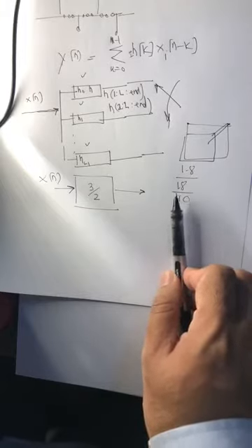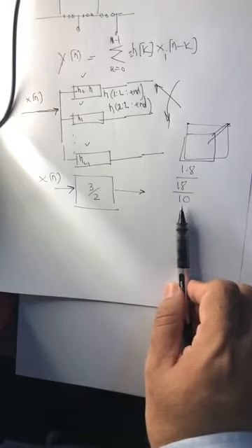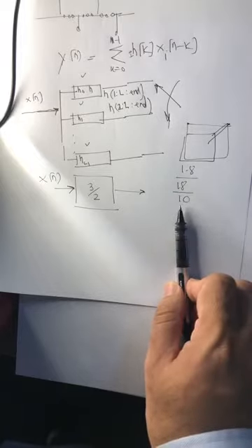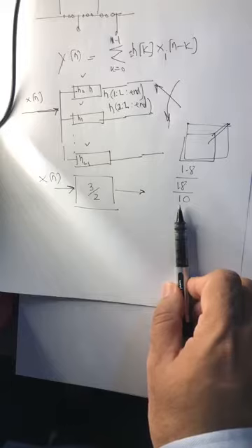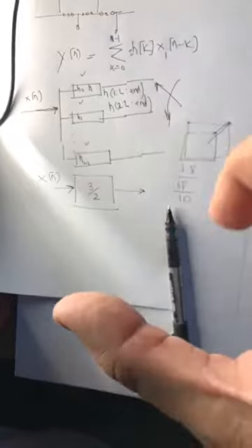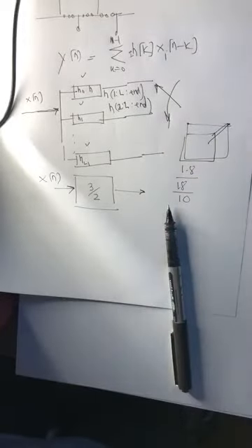Never do the decimation then interpolation, because if you do the decimation, though you are increasing the size of the image, you throw away a lot of information, and that'll basically degrade the quality of the image. So never ever do the decimation first. Whenever you are changing the size of the image like this, you got to do this in 2 steps.